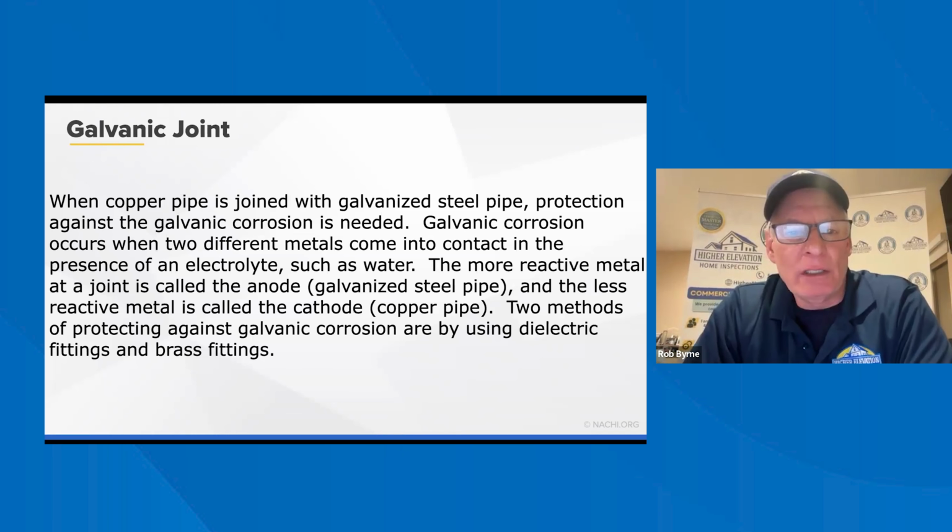One thing that we do a lot of times on the water supply line, if you have an old gate valve, we put in the report that we state the fact that they're difficult to operate. They might not function when you need them. So I always say to my clients, when you have a plumber here and you're doing a punch list, have them install a ball valve on the upside of the gate valve. So if you have to close the whole house off, it's much easier to do it with this ball valve than a gate valve.